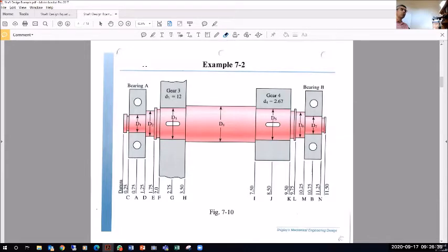Even though you were able to do it for a prismatic shaft in homework number 2. And the last thing in shaft design was to look for vibration concerns and resonance. If you know the speed the shaft is going to rotate, you can use what you learned in the vibration class to make sure that you have no concerns in regards to vibration.